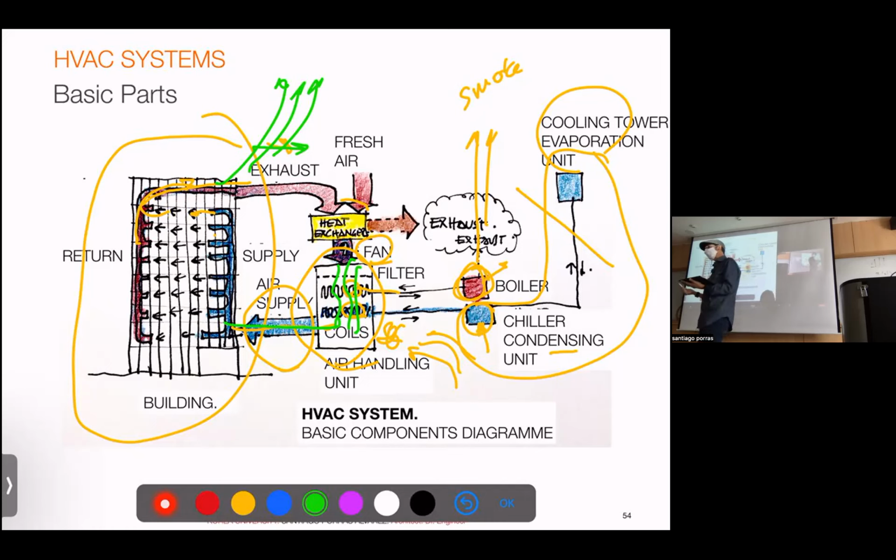That's as far as possible, so it diffuses in the atmosphere. When we tried to save energy, especially after the 70s, a percentage of that exhaust would be recycled with an addition of air from the outside, right? This is mixing a percentage of air. This is something we don't do anymore, right? Because the air you are collecting is full of dust, bacteria, microbes, smells. You want to put that again in the building. We have very high quality filters, so it could be filtered, but those filters need to be maintained, and so it's a weak point.